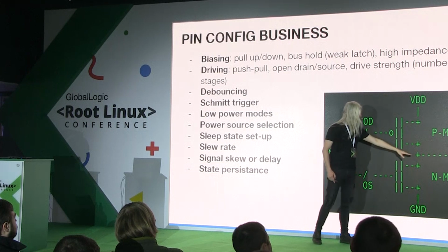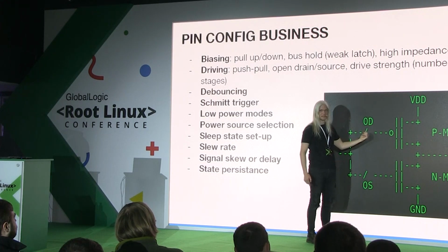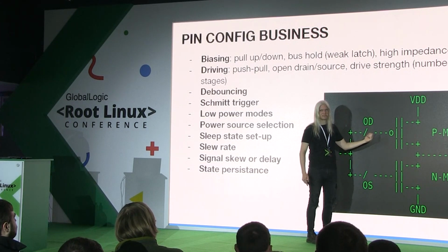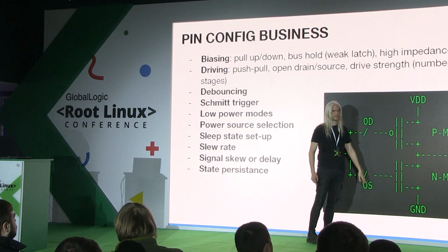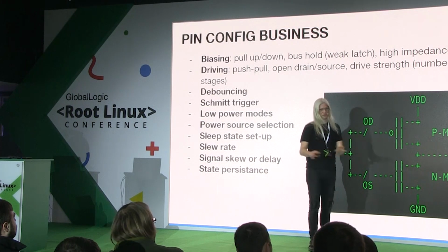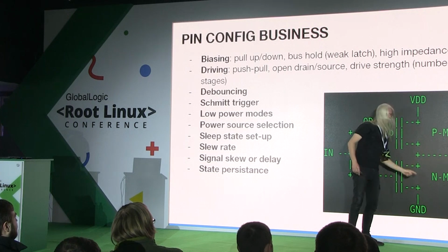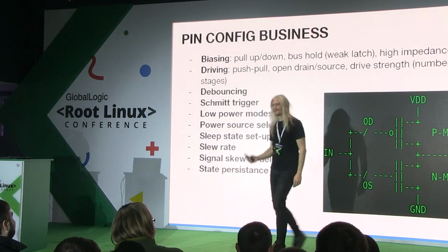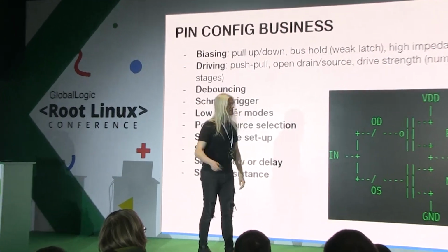If you don't close that switch, now let me think. If you open this switch, you get an open drain configuration on your totem pole, and if you open that switch instead, you get an open source. Not open source as in software, open source as in source. So you all know transistors, right? Good, thanks.